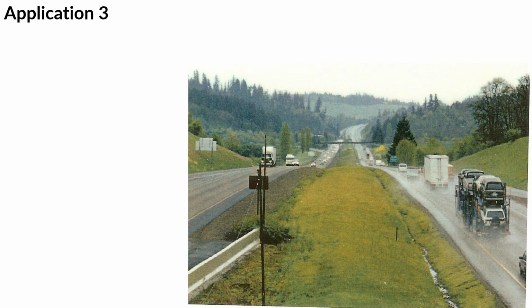Many of you have driven during rain showers on the road, and you know how the splash and the spray is dangerous because you cannot see, you can have accidents and things like that. So one of the things that road engineers would like to use is a permeable friction course, which actually lets the water go through, drain quickly, and avoid the splash and the spray.